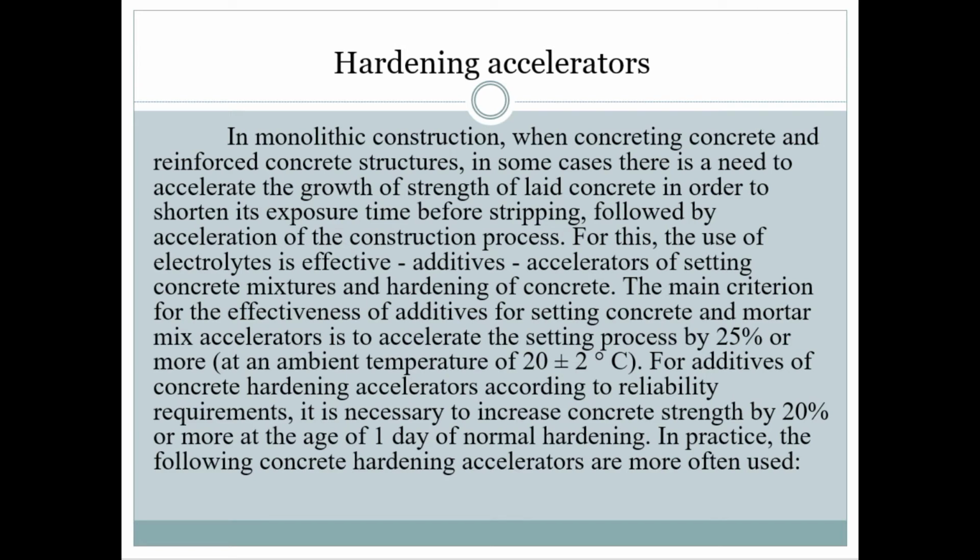The main criterion for the effectiveness of additives for setting of concrete and mortar mix accelerators is to accelerate the setting process by 25% or more at an ambient temperature of 20 plus or minus 2 degrees.